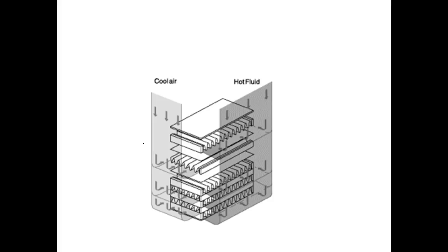Copper has a lower thermal resistance, but the mass is basically the same. You use that math to determine the size. You could swap that around and say, I need to get rid of this much heat, how much surface area do I need? So there's a lot of math involved. It's how much surface area you need to transfer as much heat as you possibly can.